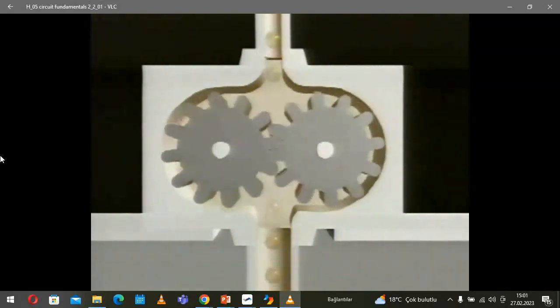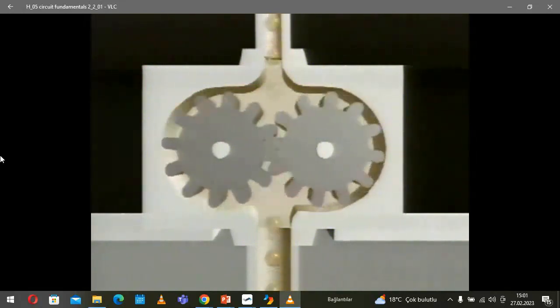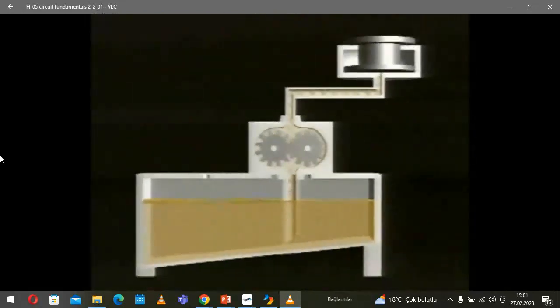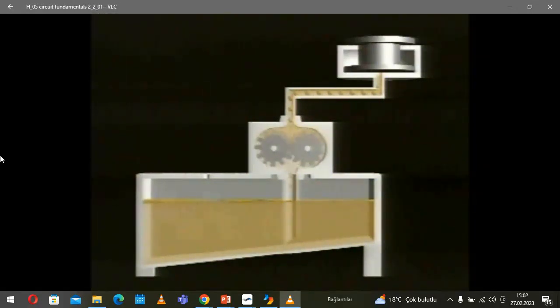Initially, the pump doesn't create pressure, but only a fluid flow. Not until the fluid meets with resistance, for example line resistance or a load, as in the case of our platform lift, does hydraulic pressure build up. When pressure is higher than the resistance of the workload, the piston begins to advance until it reaches its upper end position.